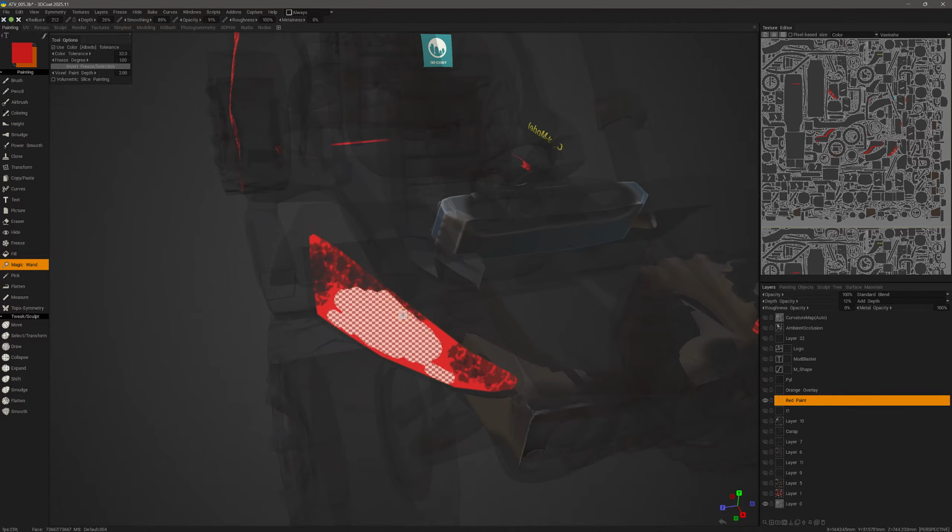Okay. Now we can't apply paint information or depth information or glossiness inside of a frozen selection because that's the nature of it, is to prevent that. But we can invert the selection and then make the change. So let's do that now. We can choose invert freeze selection. We could also choose that option from the freeze menu.